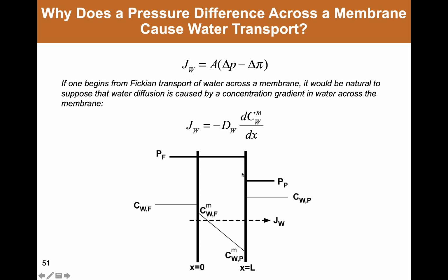And so there is a pressure gradient or pressure discontinuity at the back face of this membrane, and any penetrant that is sitting in the polymer right at the back face is experiencing the feed pressure, and penetrant that is in the water or solvent phase just next to the membrane is obviously at the lower permeate pressure. Turns out this pressure discontinuity is incredibly important in setting up this concentration gradient, and therefore the Fickian driven transport of solvent through the membrane.